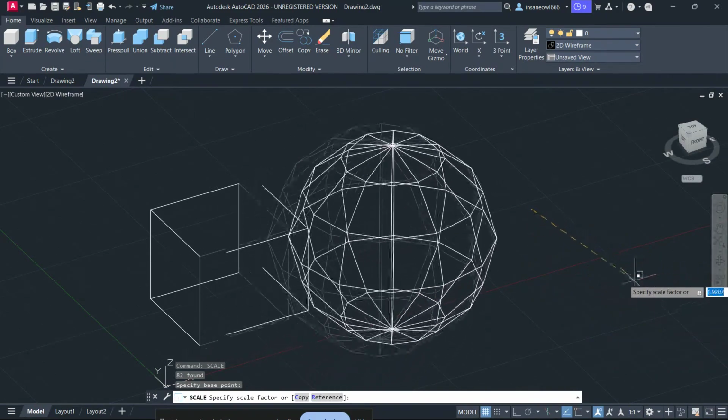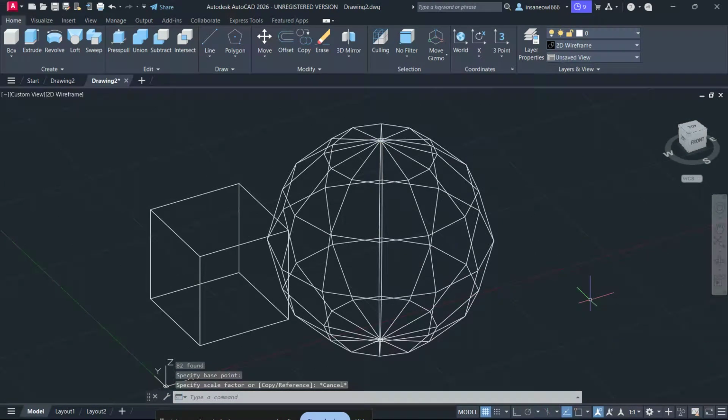If you are working with imported files, always consider whether the issue started outside AutoCAD. Models from other software can bring in imperfect geometry, hidden faces, or invalid edges. In those cases, combining the clean body step, the solid check, and the scale workaround usually gives you the best chance of success. The key is to test one fix at a time so you can identify which one actually resolves the problem in your file.